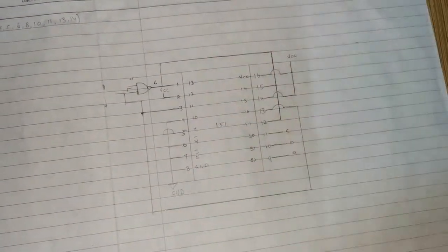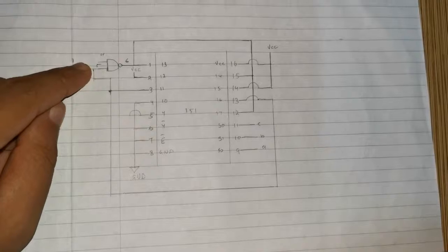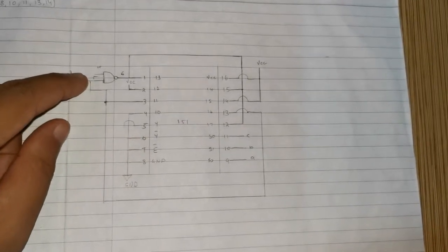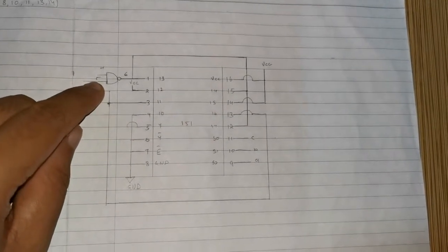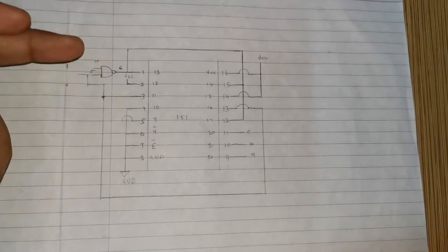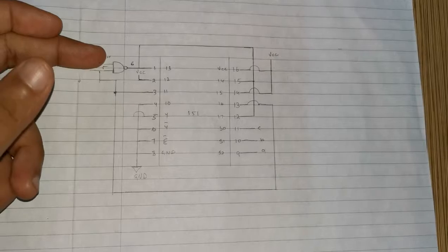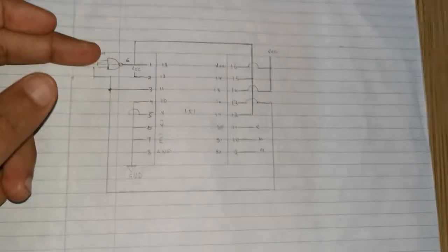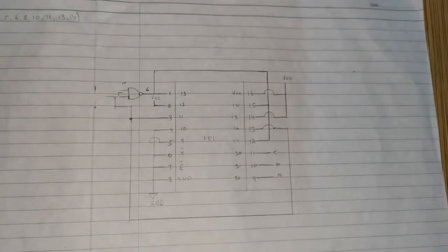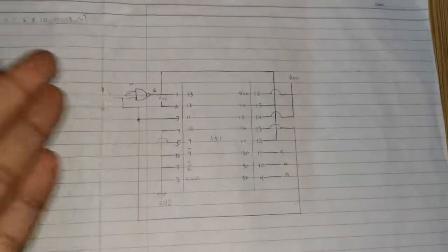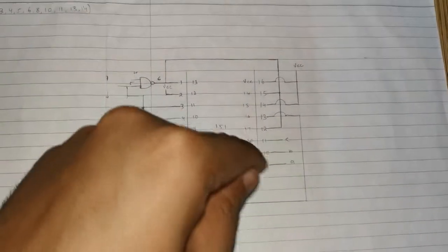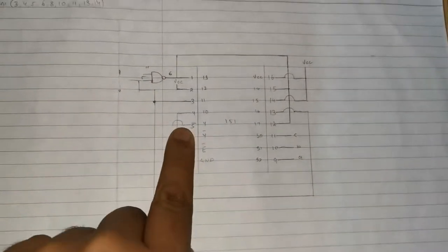So over here is the circuit that we've created. This is the NAND gate that I was speaking about. Basically, this input is just connected to the VCC, whereas this input over here is connected to the D switch. So the logic is acting as a simple inverter. It's just turning D into not D. 11, 10, and 9 are A, B, and C switches, and number 5 is our output to show our light.